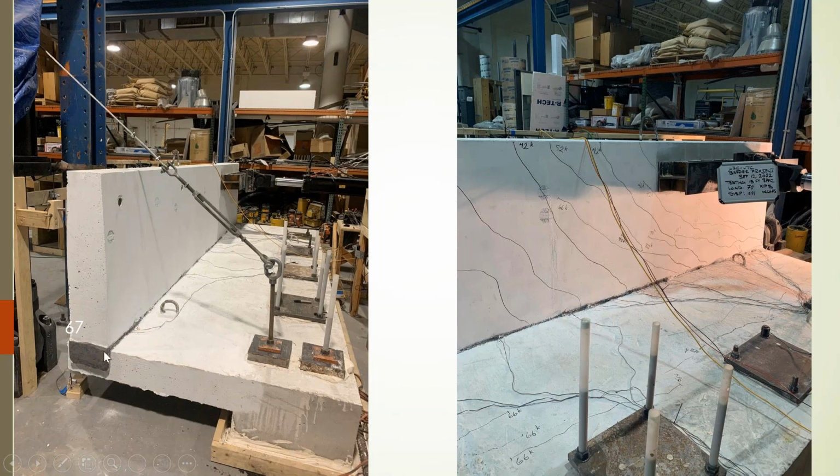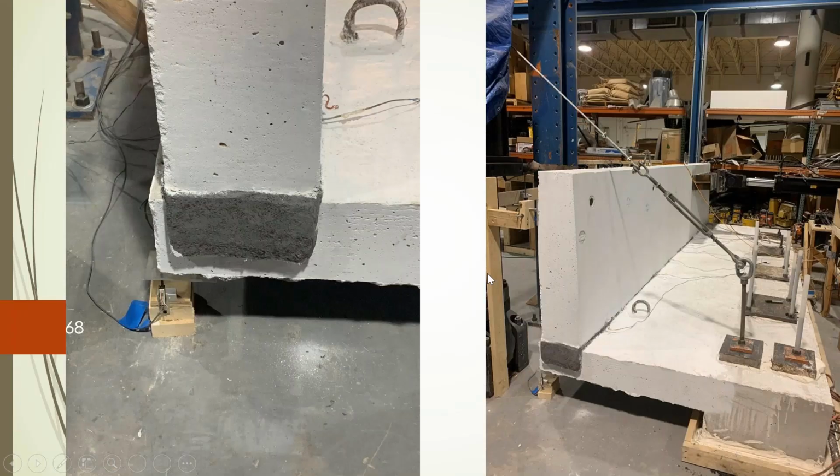I can tell you this is how we connected the vertical element to the horizontal with the UHPC. Those of you who are familiar with barrier design, just connecting this cast in place, you will not get more than 70 kips. The only way to go more than 70 kips and reach what AASHTO predicts is using UHPC. This was just a test that was conducted yesterday, and we hope to share more results on this.